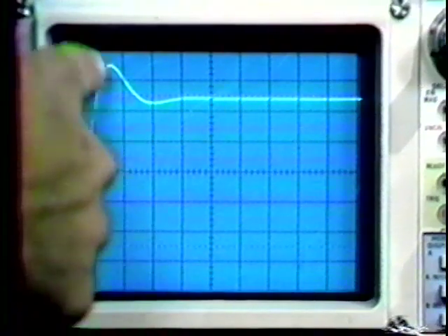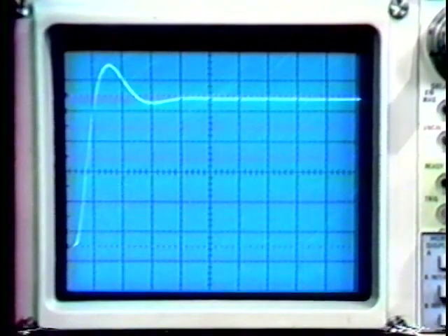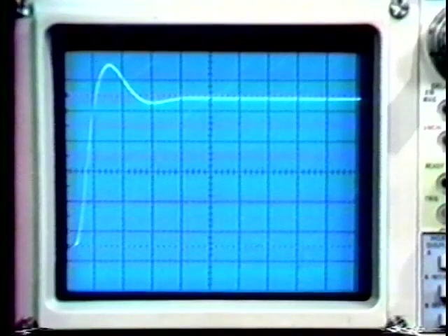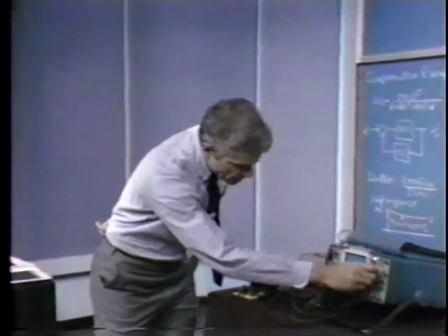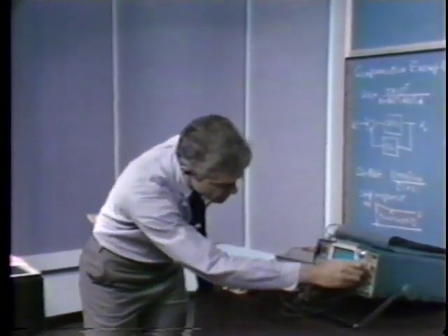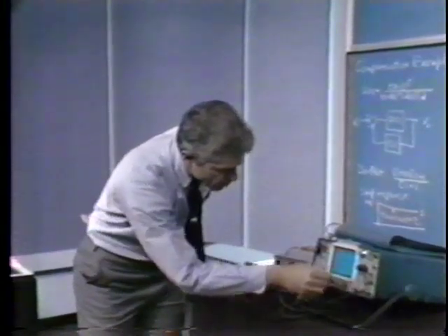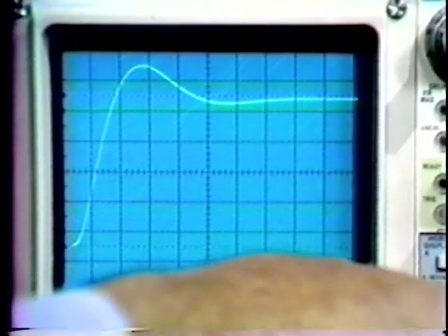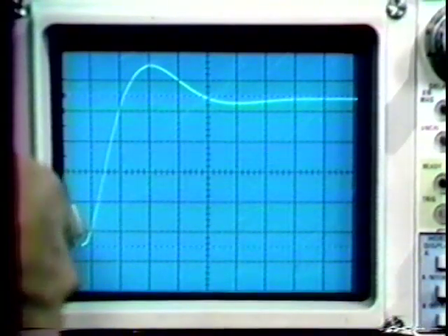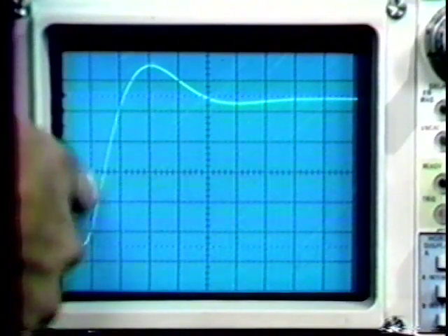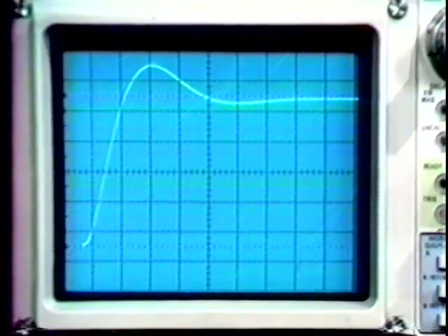When we do that, we first of all note that we get about 20% overshoot from our step response. So now we have the P0 that's the same as the lag compensated case. We anticipate that that should be true in that these systems have identical phase margins, or as nearly identical as I could make them. If we measure the response, the rise time, well, let's see. Here we're at 50 microseconds per division. Let me just move things around a little bit. And we see now that we have just about a 50 microsecond rise time.